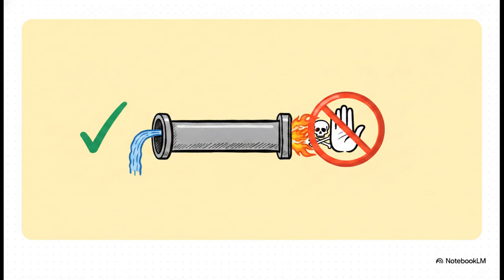Moving in to Section 5, Service Limitations. This is where the rules urgently shift from how to build it to where you absolutely cannot use it. The real-world limitation placed on cast iron is intense. For Class R and B exchangers under RB 1.61, cast iron is strictly limited to water service only, and pressures cannot exceed 150 psi. You literally cannot use it for anything else.